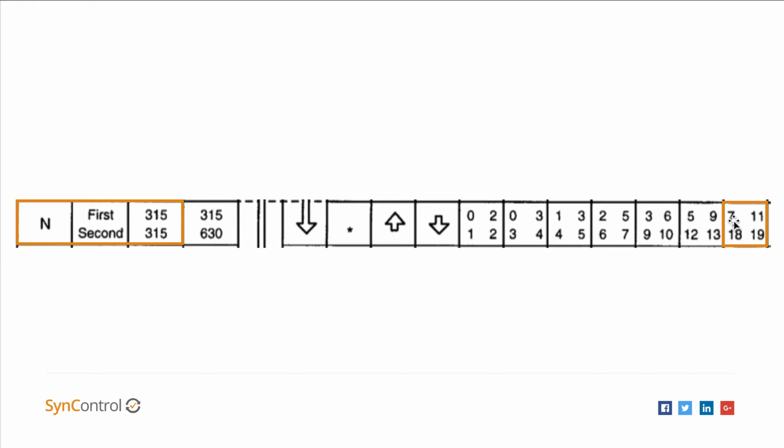Then either it's very good, meaning 7 defects or fewer, it's accepted. Or it's very bad, meaning 11 defects or more found, then it's rejected. Already no need to go to second step. But if you find 8, 9 or 10, it's not clear, okay? You only took 315 samples, and in the single sampling plan you would have taken 500 samples. So you're really trying to find a conclusion based on a small sample.